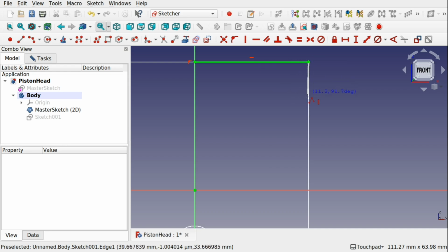And we're going to use this line. Now I could import this line if I so desire. As a matter of fact, I'm going to do that. Let's hit escape again, and let's import this line as well. This makes life a lot easier, because I can use the polyline tool, connect to that point, and use this line like so, and create a number of grooves. Connect to the line, connect to this line again, and next groove, and last one.